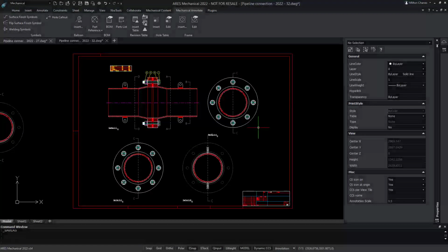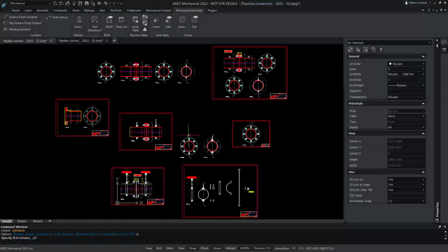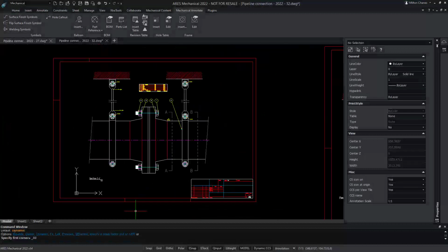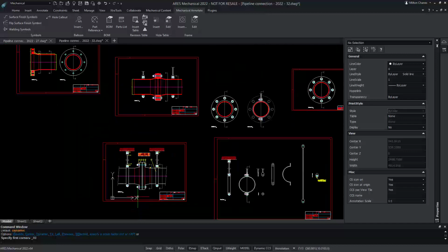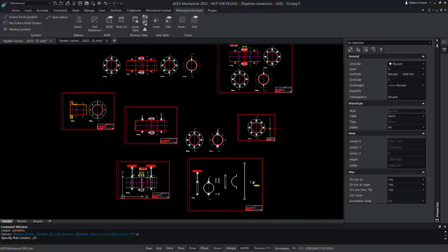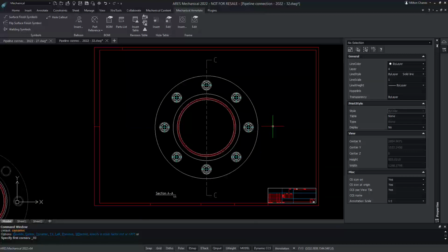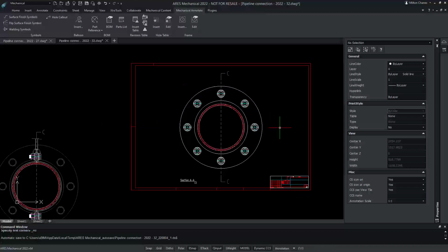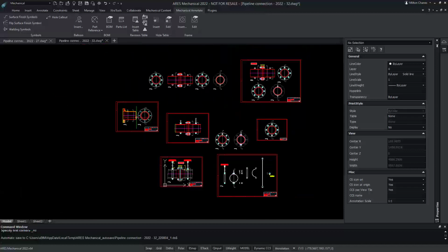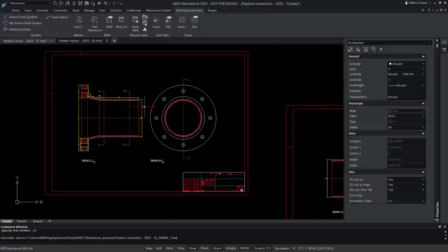A mechanical drawing, like any technical drawing, needs to be represented with sheets that will be configured for printing. In this demo, we will first see the traditional method to create multiple frames in the model space, and next we will see the modern approach to use layouts, annotative scaling, and sheet sets.